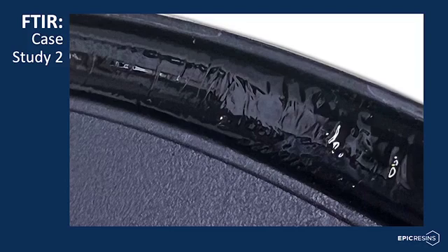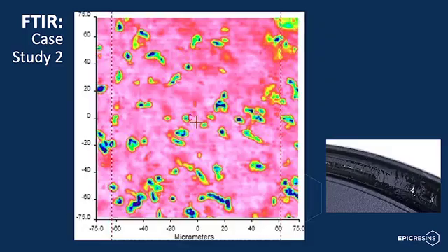The second demonstration of the utility of the ATR microscope was an instance where a customer was observing inconsistency on the surface of their potting material at the completion of their curing process. The image here shows what the customer was observing. We again started this analysis by sectioning the potting compound in the suspect areas. Upon analysis, the following ATR microscope absorbance pattern was produced.